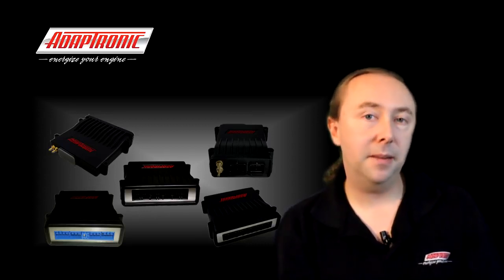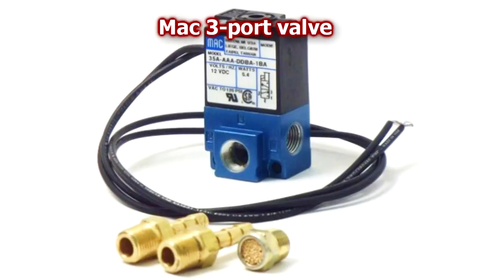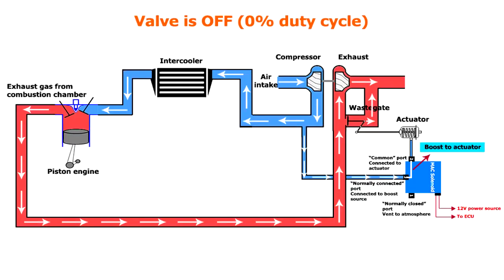Now there are several ways that people control the boost on these type systems, but we'll just talk about the 3-port solenoid method. So in this method you have a 3-port solenoid where you have a common port which is normally connected to the normally connected port, so air just flows straight through it, and then when the solenoid's energized, the common port connects to the normally closed port instead.